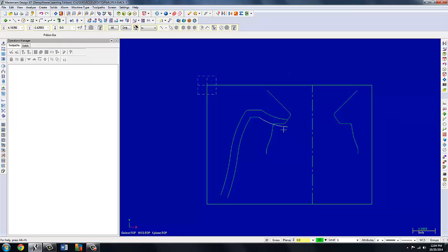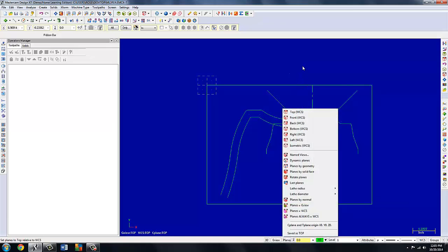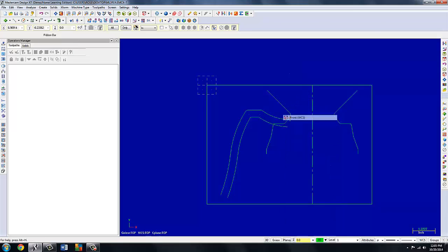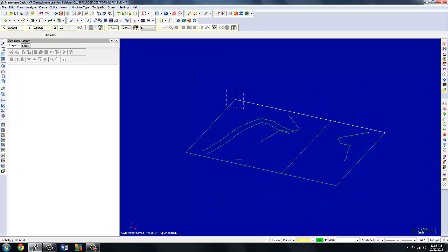First instinct is to trim this, but we don't want to do that. We'll let the fillet that we're going to create down the road between the two surfaces handle the fillet. But before we can create those surfaces, we need a contour. So I'm going to change views, I should say construction planes, and we want to work in the front. We see this did change, and I'm going to roll up on this.